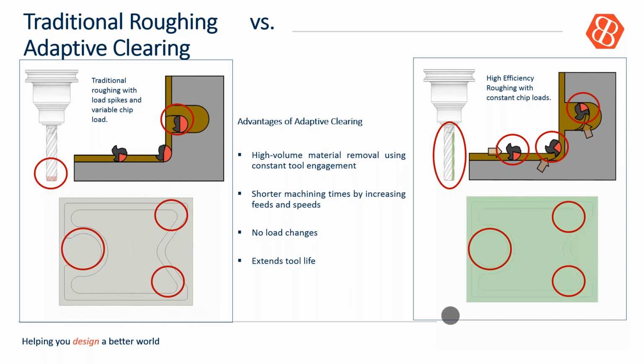As we listen to the cut, we can hear that change in load coming into the corners and driving into slots. And monitoring the data coming in from our sensory tool holder, we see the spikes in load. So to maintain high feed rates, traditional programmers would take a light depth of cut. Unfortunately, this technique overuses the bottom of the cutter.